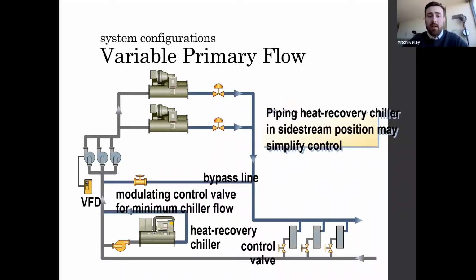A possible method for loading a chiller preferentially is to install it in a side stream location and vary the water flow. When varying the water flow, heat recovery capacity control must be accomplished by changing the pump speed rather than adjusting the chilled water set point. While this is theoretically possible, maintaining constant flow through that side stream chiller and changing the set point is simpler. The chiller also operates more efficiently at higher evaporating and leaving water temperatures.